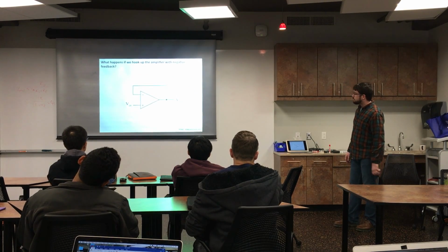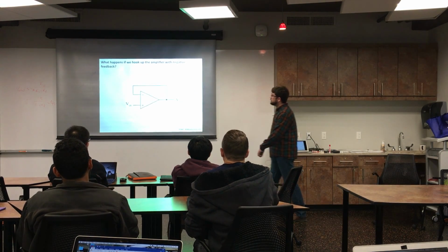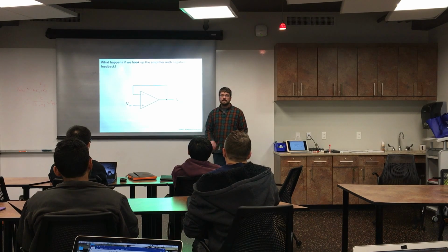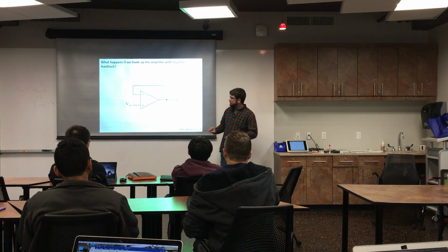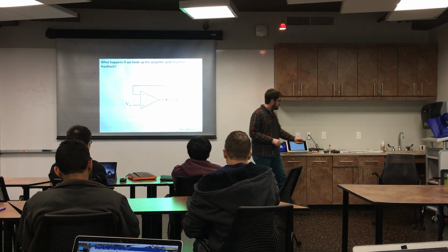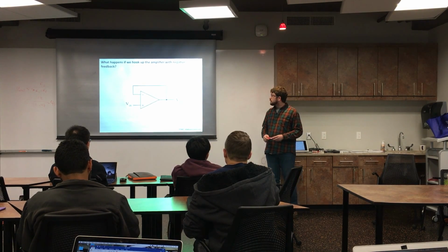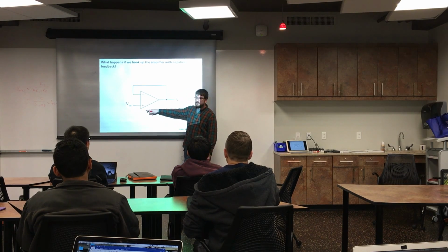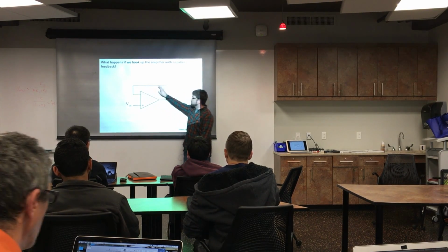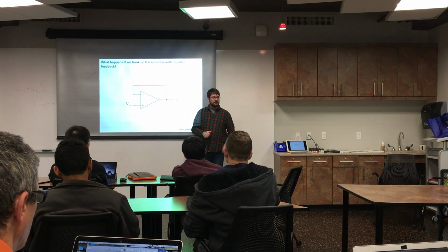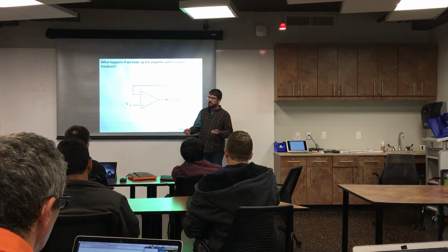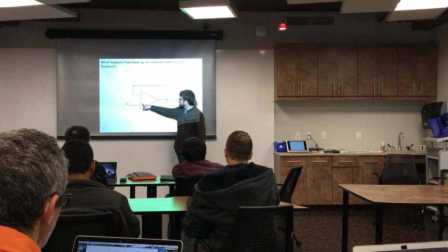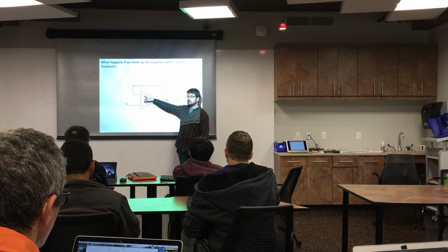Okay. So we looked at this circuit, which was a voltage follower. And I think a few people maybe didn't quite follow what exactly was going on in this circuit. So let's look at it again, thinking of it in those terms. So we put some kind of voltage in here. Let's say we put 1 volt in. Well now, and we assume in most of these circuit analyses that everything starts at 0. It's a nice starting point. So right now, we've got 1 volt here, 0 volts here.